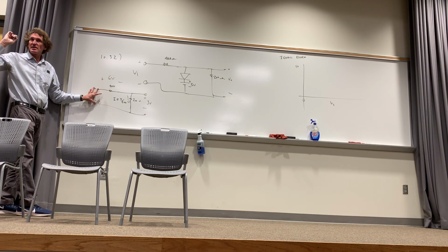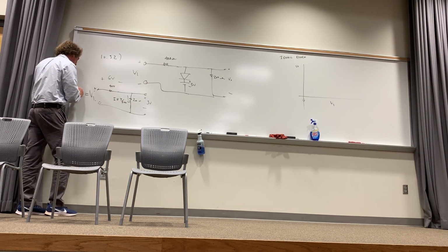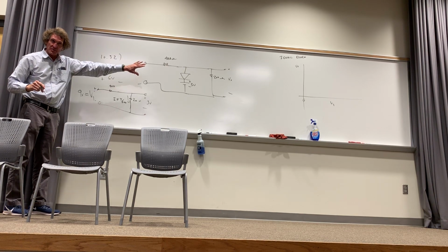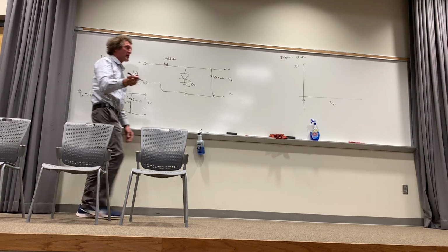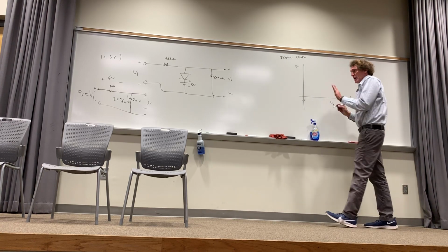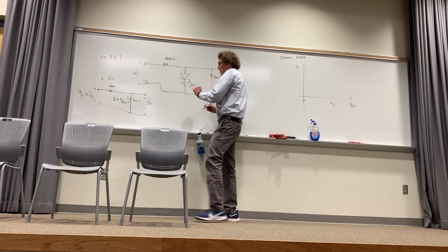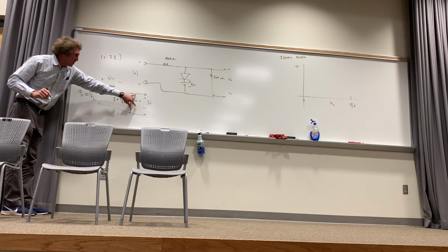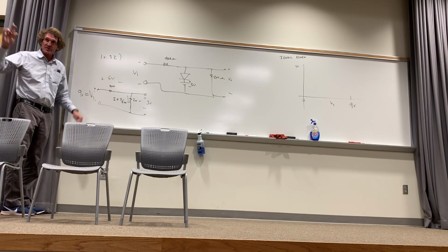This is an easy thing to see, but an easy thing to miss. Now, that means until the input voltage is 9 volts, the output voltage will be unaffected by that combination. Do you all agree with me? So now I come up here and I say, all the way to 9 volts, wherever that is, I know that the output voltage is just what? If that's the output voltage, it's only based on voltage division, isn't it? How many see this right here?